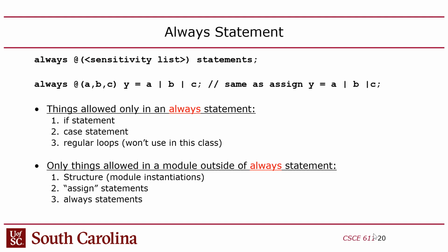In hardware, all of that would have to be performed by a clocked always statement that would keep track of what's going on on the bus in each clock cycle, because the bus protocol is a sequential process, right? You have different things going on at different times whenever you do a bus transaction, and so you need to use an always statement for that. So it's important that you guys be comfortable with that.